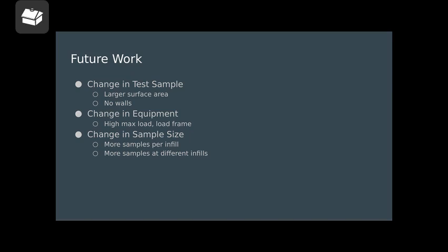It would be nice, in a perfect world, to have 10 to 20 samples of each infill percentage going from 1% to 99%, giving us a great view of how infill directly affects modulus, which probably would significantly reduce error, as we would have a very wide swath of data to pull our numbers from.